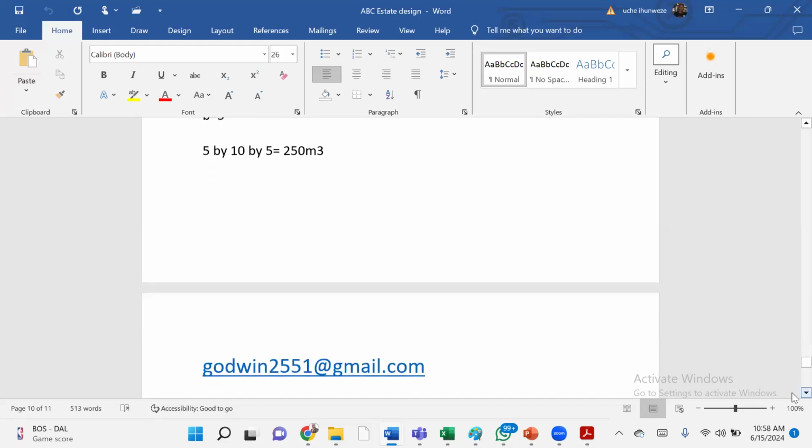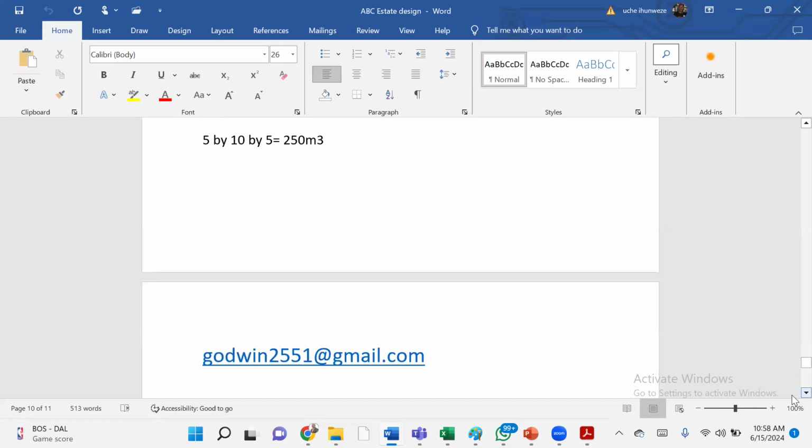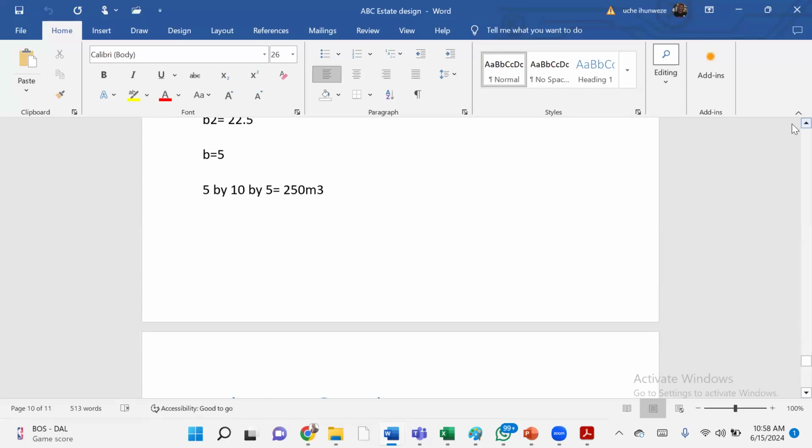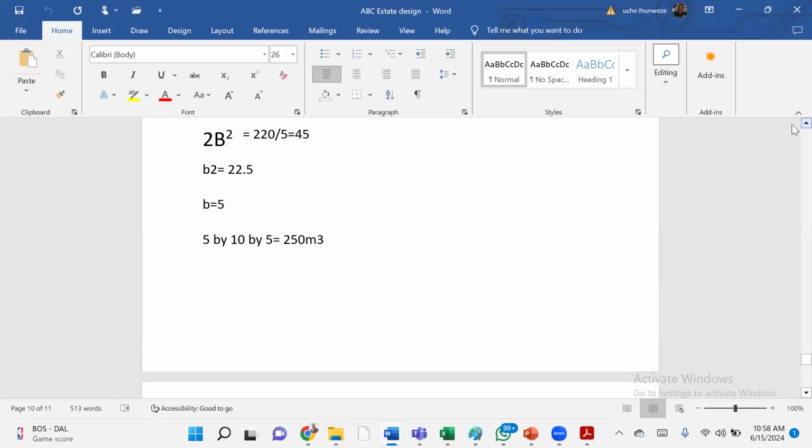But there's something you need to add. There's what we call fire requirement, firefighting requirement, and then there's what we call equalizing volume. When I got this value, I need to add 2 extra parameters. There are 3 parameters that make up the overall volume of a tank. It is in your test. You must add 2 other parameters, and those are the equalizing emergency volume, which is about 20%. In other words, if you get your tank size to be 100 cubic meter, you just assume 120. Let 20 be emergency volume. That emergency volume could be fire, it could be repair, it could be an impromptu party.